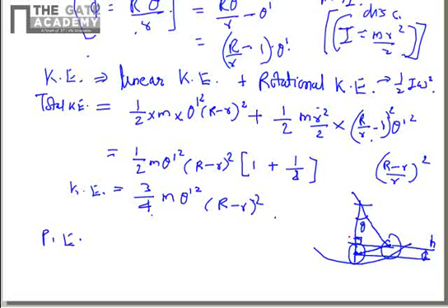If you draw this line and you get a perpendicular on the initial line, the equilibrium position line, and you have the radius equal to R from the center, then this center to center distance is R minus r. So in this triangle, if you see, you have this R minus r distance, theta, 90 degrees, and then R minus r distance again.